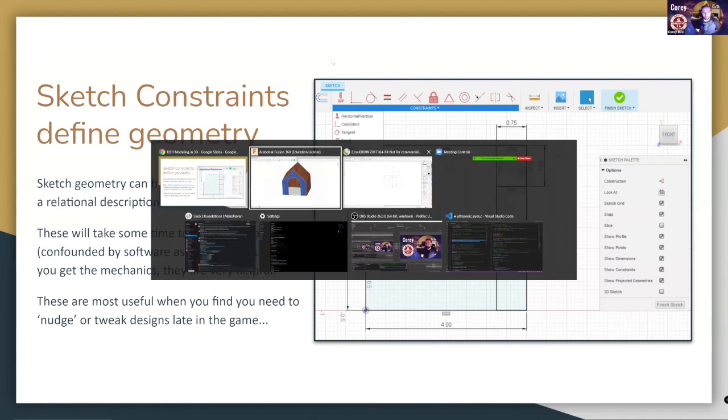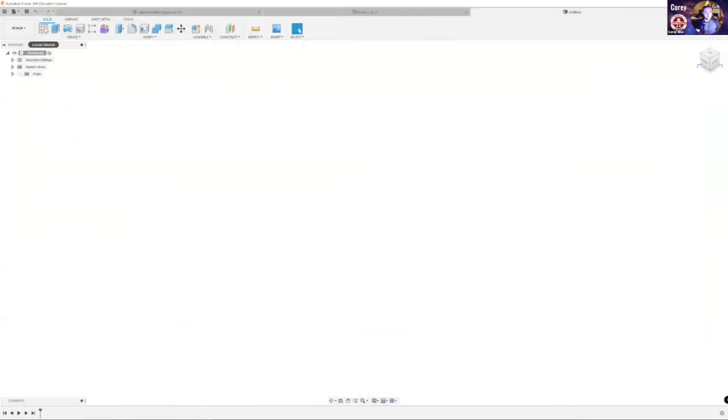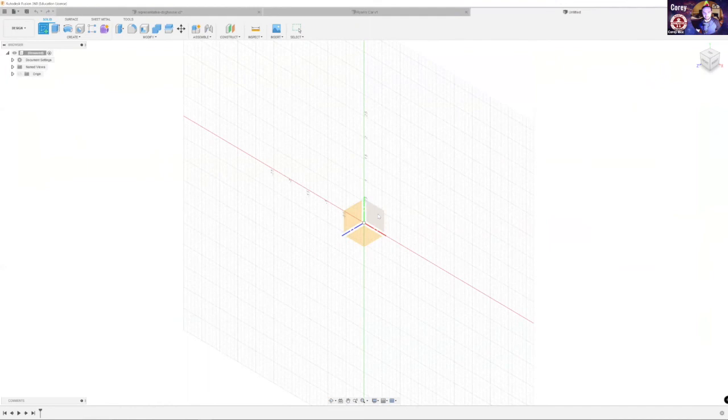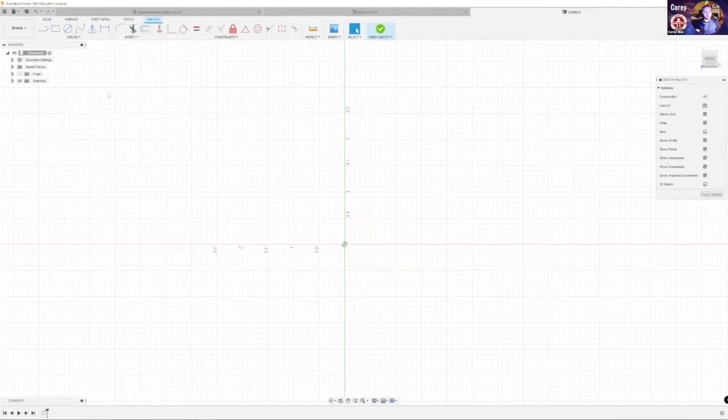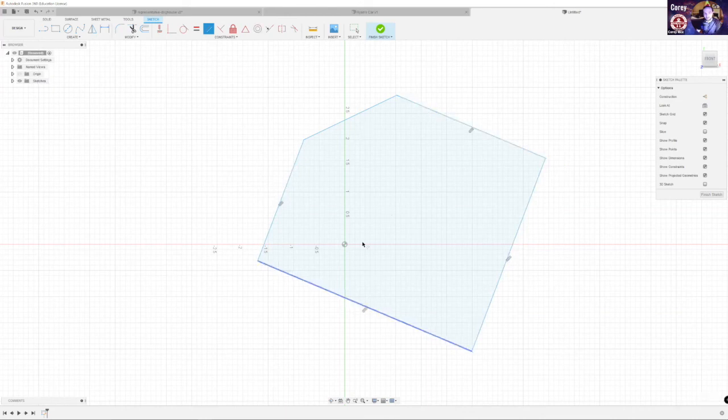And so there's lots of interesting applications for this, where if I'm drawing something, we'll draw something on here. I can start to draw in lines, put them all together in weird ways. And in this case, I can say, well, I want you to be parallel. Like I could define this line and this line to be parallel, and then they pop into existence that way. And those two to be parallel.